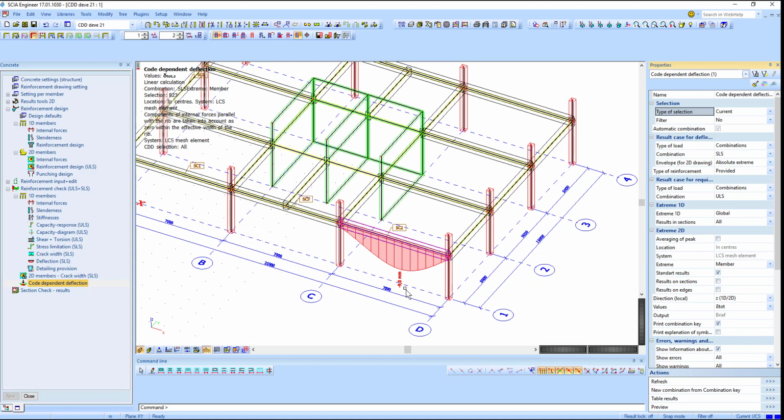So you can see the difference between 3.1 and 9.0. This is just because if you select one member, then we take the real stiffness in that member and some linear stiffnesses around it. If you selected everything, then the result will be accurate.